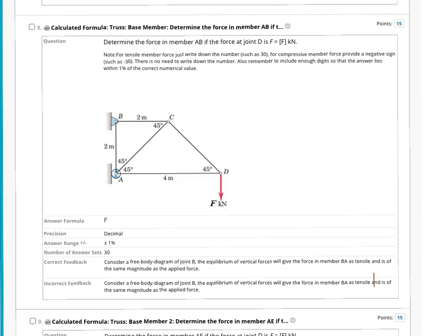For this particular problem, what we have to do is find out the reaction forces at A and B. So the reaction forces at A, let's say it is a roller, goes from left to right, and at B it's a pin, one force goes from left to right and another force goes upward direction, let's say. Let's name them R1, R2 and R3.